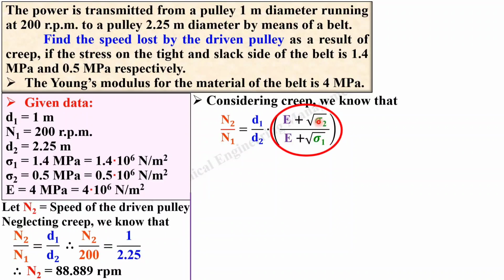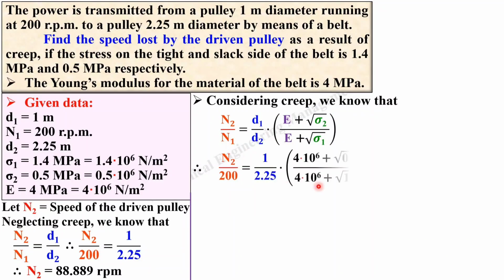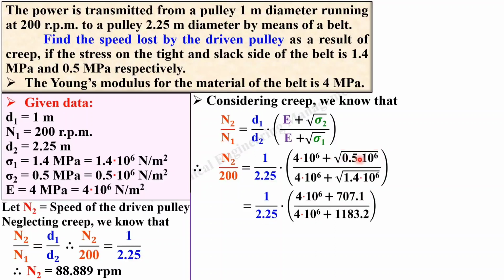Keep in mind that in the numerator it should be sigma 2 and in the denominator sigma 1. Always sigma 1 is greater than sigma 2, and you know that sigma 1 is the stress in the tight side and sigma 2 is the stress in the slack side. Now put the values over here. N2 is our objective and the remaining data is given to you. Now simplify it. If you take the square root of this, you will get this. Now you can find N2 from this equation. So you will get N2 equal to 88.878 rpm.